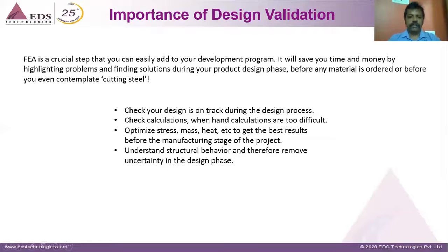Let's see the importance of design validation. FEA is a crucial step that you can easily add to your development program. It will save time and money by highlighting problems and finding solutions during your product design phase, before any material is ordered or before you even contemplate cutting steel. Check that your design is on track during the design process. You check the calculations, and when hand calculations are too difficult, that is where you go with FEA, using the digital validation process.